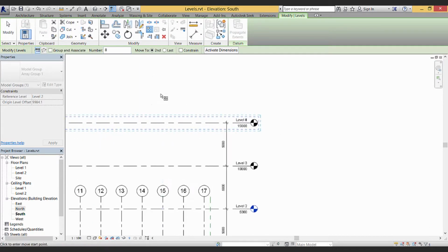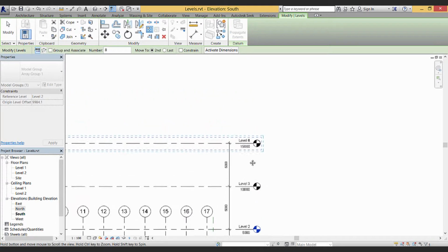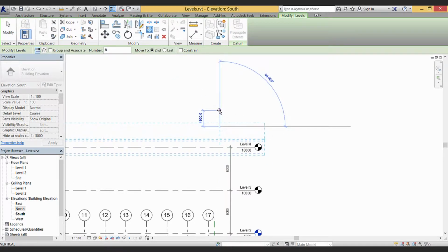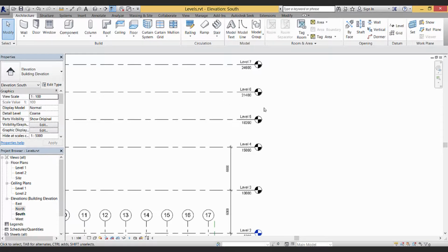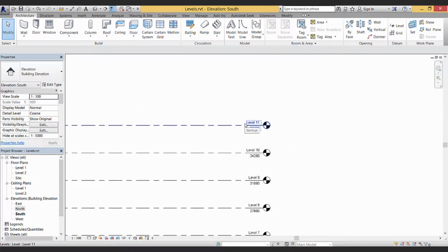And then I'm going to have a pretty high story height on level 1, 2, and 3. And then from level 4 up, we're going to have some hotel rooms, so with lower story heights. I array this level 4 up, let's say 3.2 meters, like so. Then you can see that level 11 now is the last level